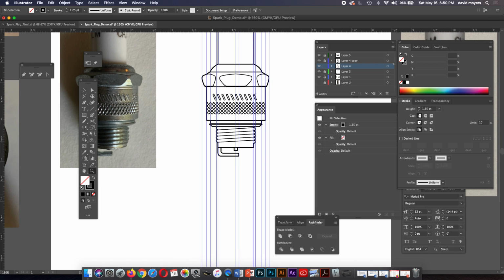Okay, now, let me get my ellipse tool. And we'll go down here. Make sure we're on the center point. Hold down the Shift key and the Alt key. We'll draw a first circle here. Okay. Now that circle, that's going to be the outer contour. So it's going to be that. Now, we can keep just drawing circles. That's one thing we could do. Or we could do copy, paste in front. They both work.